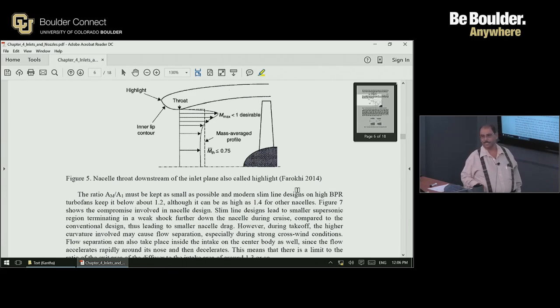the takeoff performance of the aircraft, which means the engine maker has to produce a version for the later versions of the aircraft that can provide an increase in thrust by whatever percentage. And usually you don't want to redesign the nacelle. Remember, the engine is also the same, except that maybe they will push up the TT4, for example, by suitable modifications of the engine to produce a higher thrust. So the engine is the same.